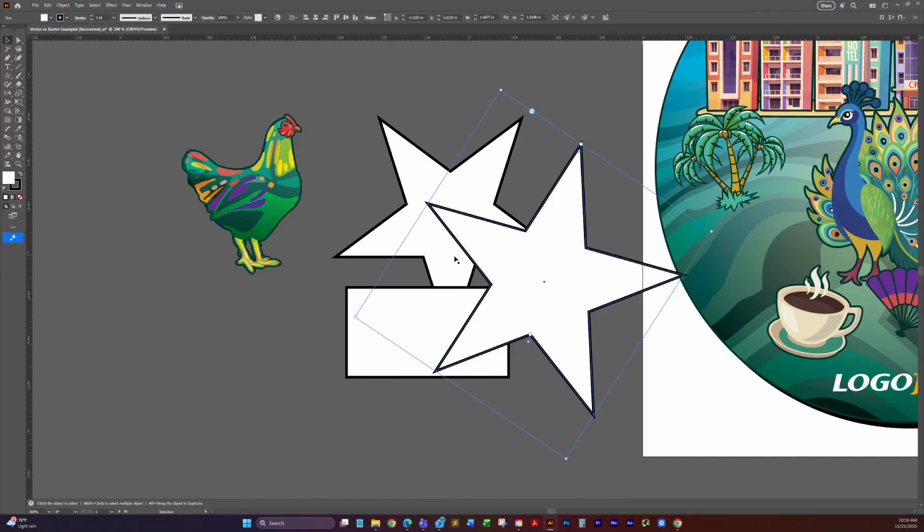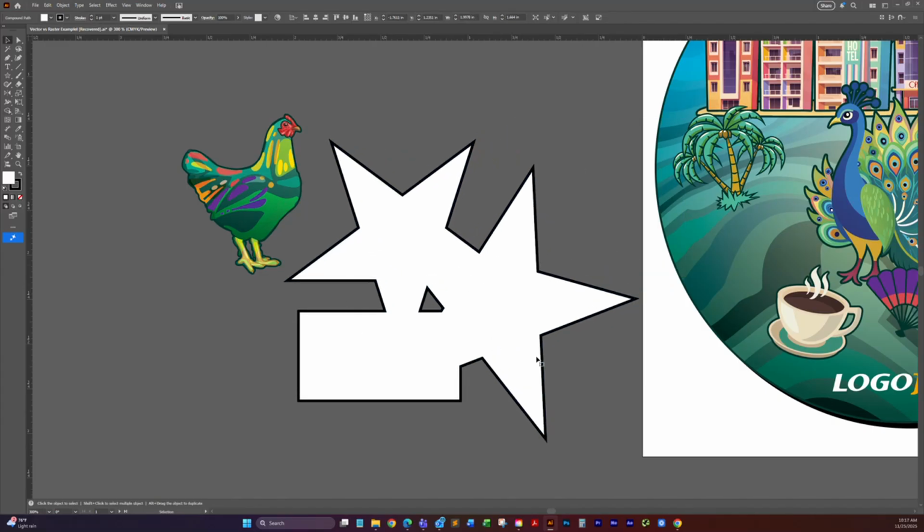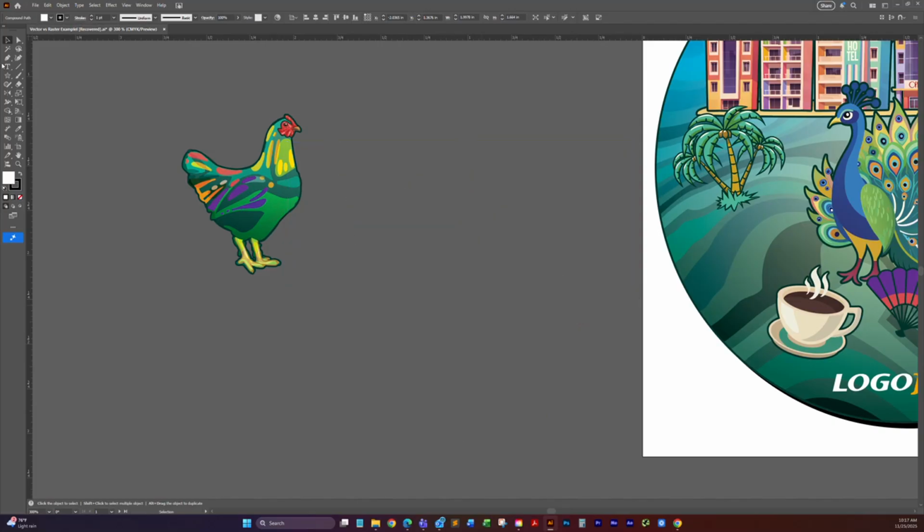Say I wanted all of this, or some of this, to be connected. And how do I connect all of these? So you can go to Shape Builder tool, and you can see how it kind of highlights different areas, and you can just drag across areas that you want to be in the same shape, and you can see how it merges those shapes together. And I just created one grouped together shape, which is really neat. In some applications, it can be very handy.